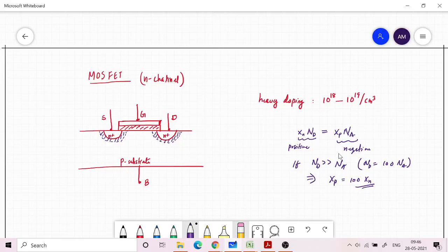So now yesterday I told you that we will take source as a reference, and two potentials that we apply. One is called VGS, so that is this voltage. VGS is the gate to source voltage. Source is grounded, and then the other one is VDS.